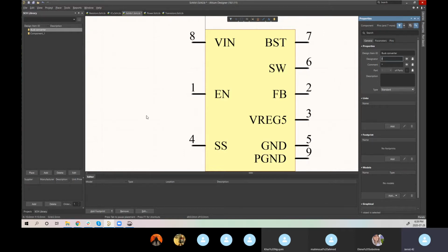Designator. There's a big list of the standards. So for resistors, it's R, capacitors C. For multi-pin chips, ICs, and all of those, it's typically just U, and then you do question mark. By doing this, a letter for whatever the actual symbol is representing, so in our case it's an IC, so we say U, and then we place the question mark.